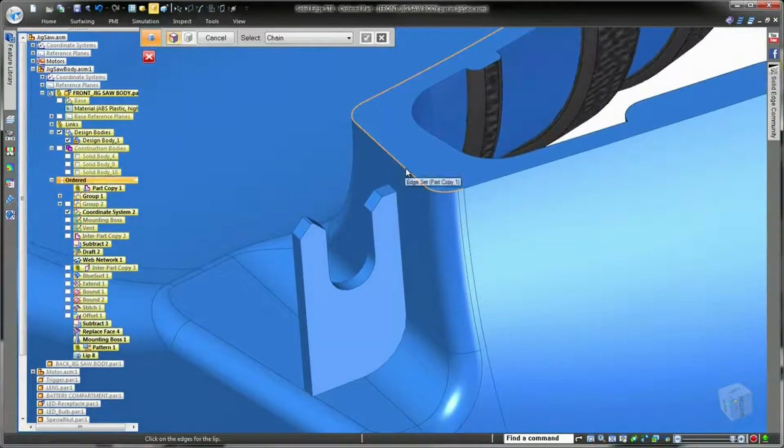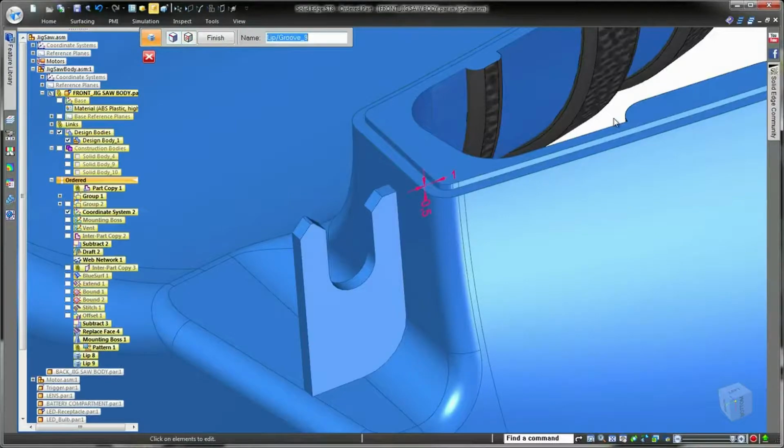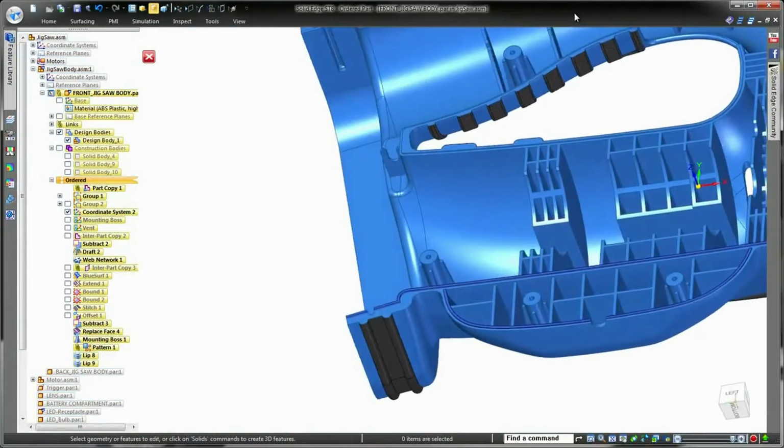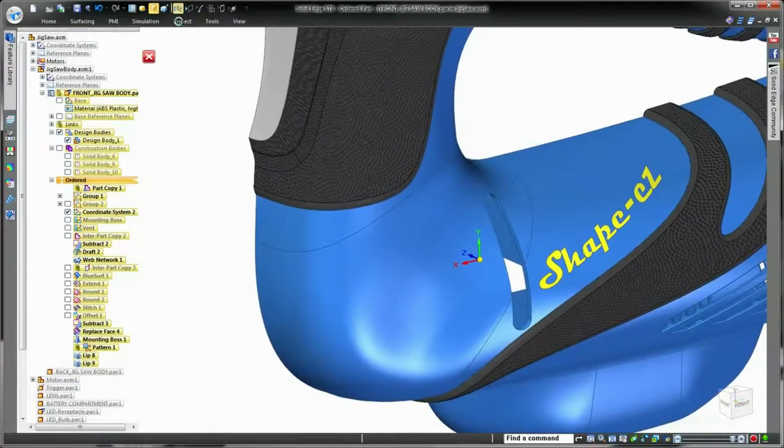As we pan to the center of the handle area, we'll generate the same dimensional profile, yet by simply adjusting the location of the profile into the part, we can quickly generate the complementary groove below the edge. The final plastic part feature we will create is a vent.